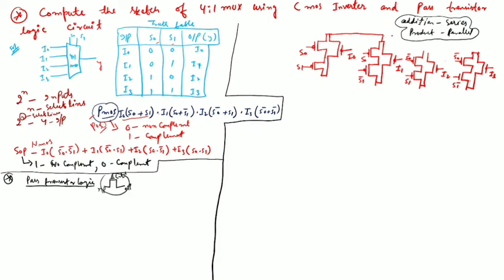All will connect from the upper side in parallel, and this all represents the POS equation in the PMOS. All these PMOSFETs are connected, and from the bottom side they are also all connected to each other. This is the pull up circuit of this 4:1 multiplexer.